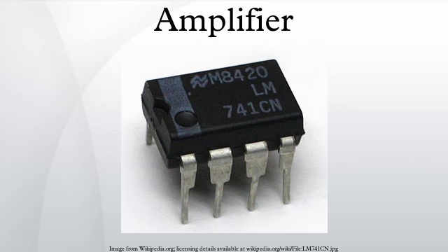or single-ended output stages. Vacuum tube amplifiers. According to Simmons, while semiconductor amplifiers have largely displaced valve amplifiers for low-power applications, valve amplifiers are much more cost-effective in high-power applications such as radar, countermeasures equipment, or communications equipment. Many microwave amplifiers use especially designed valves, such as the klystron, gyrotron, traveling wave tube, and crossed-field amplifier, and these microwave valves provide much greater single-device power output at microwave frequencies than solid-state devices.